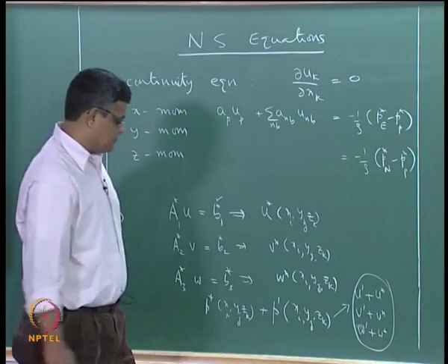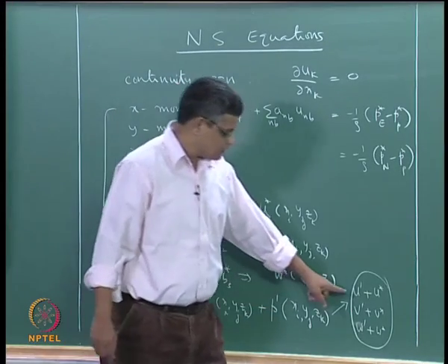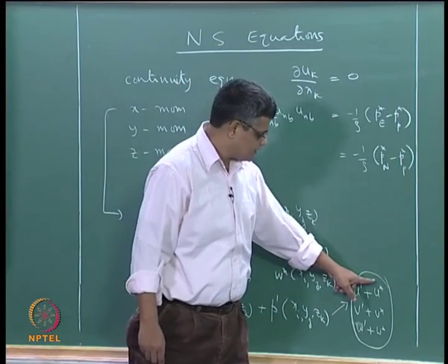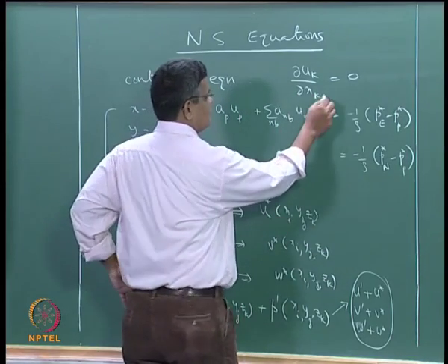So the condition for evaluating the pressure correction is that the induced velocity corrections will satisfy the continuity equation, the discretized form of the continuity equation, and we can